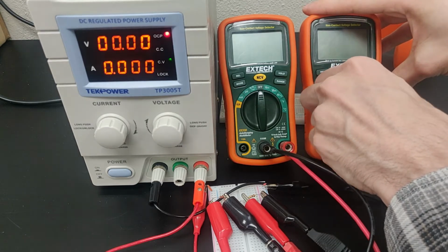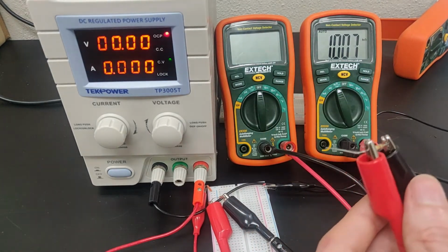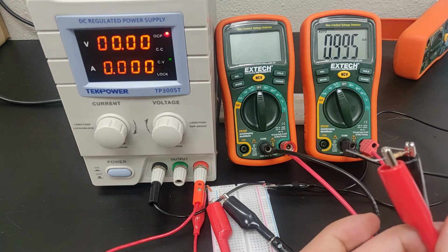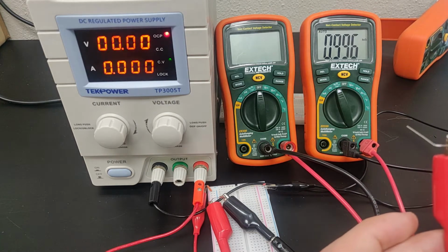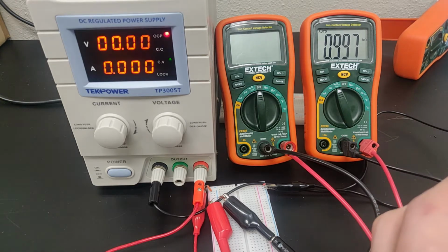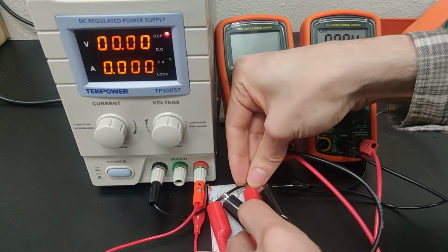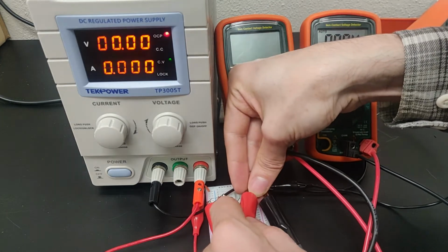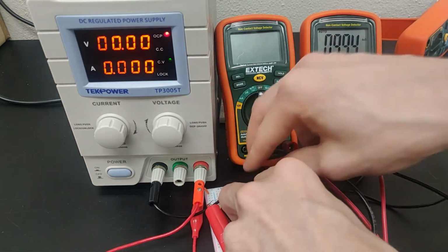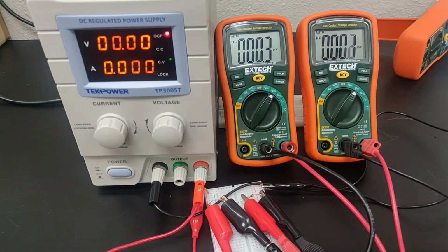Let's start by measuring our resistance for our resistor. So we'll just take it out of the circuit, and we have a value of 0.997, I guess. Yeah, we'll call it 0.997 kilo ohms. So let me just attach this back in. A lot of wires. All right, I think that's good. And switch this so that it's measuring the DC voltage.